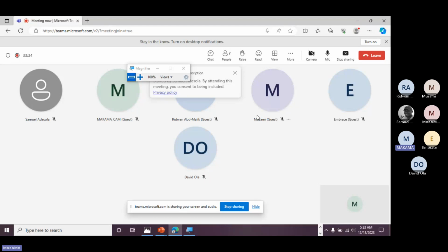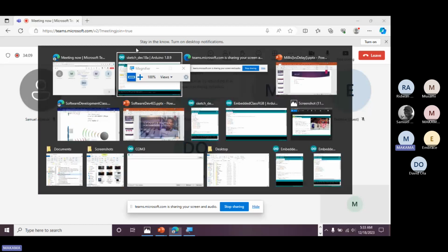So how can you tackle that problem? Because now we know our range is 0 to 1023 for our analog potentiometer. But what if that data is coming from a sensor whose output range we don't know? They used to output signals that are kind of confusing, with high values and low values. How can you tackle that problem, and convert the range of the sensor value to a particular 0 to 255, or some range you want it to be? So how can you do that?